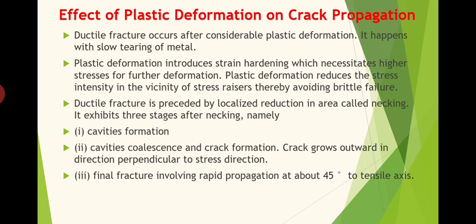So whenever there is a weak region within the material, neck formation will start within that weak region. Anyway, the starting point of the ductile fracture is the neck formation.